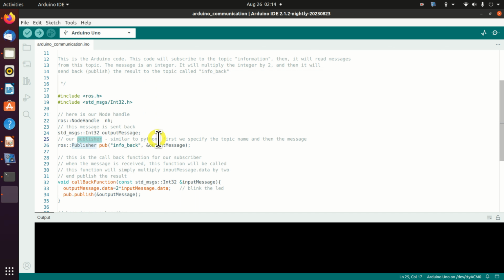Over here is our publisher. Similarly to Python, first we need to specify the topic name and then the message. And note over here what's being written. It's written infoback. Now, if you go back several minutes in the past, you will notice that the name of the topic that I specify in my subscriber is infoback. That is, Arduino will publish integers to this topic and my subscriber will actually subscribe to that topic in order to receive the messages.